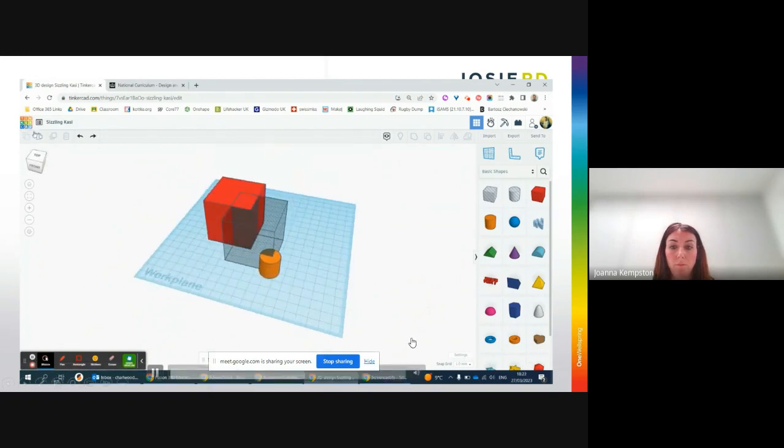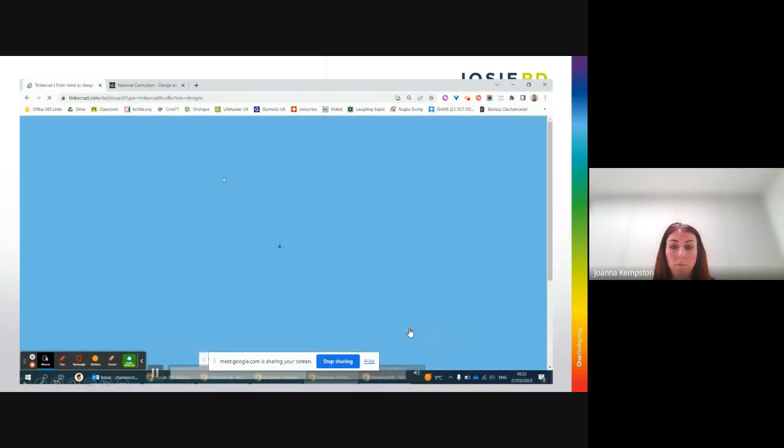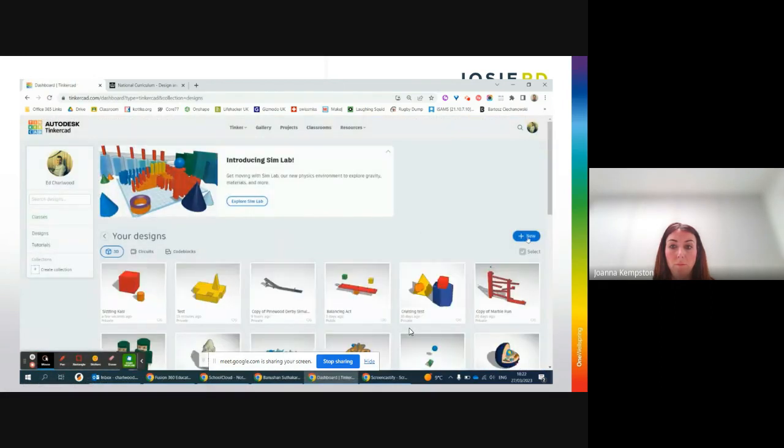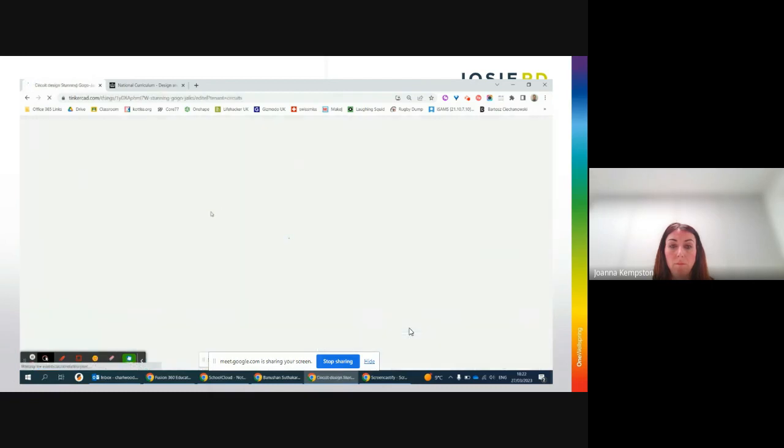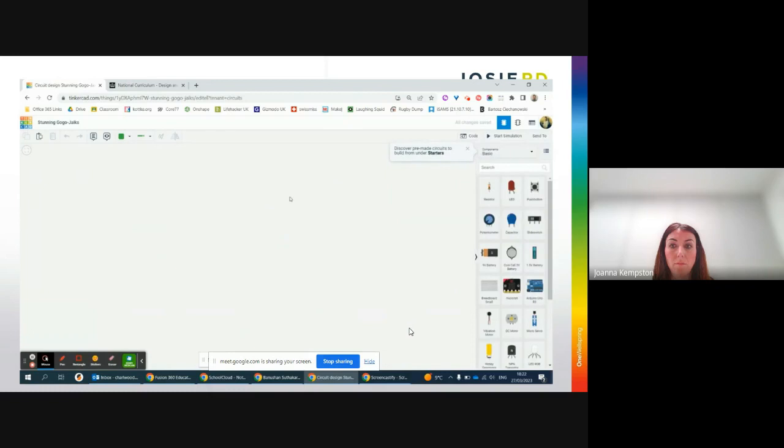The second thing I want to show you, Tinkercad, is what's called Tinkercad circuits. The same approach again, I'm going to say new, let's say circuit. In a Tinkercad circuit, you'll see the screen looks kind of the same. Instead of being a 3-dimensional workspace, we're a 2-dimensional workspace. What I can do in here is just drop different parts in. A resistor, LED, push button, a battery, and then I can see what happens when I wire them all up. In this case, I'm going to wire up my circuit,